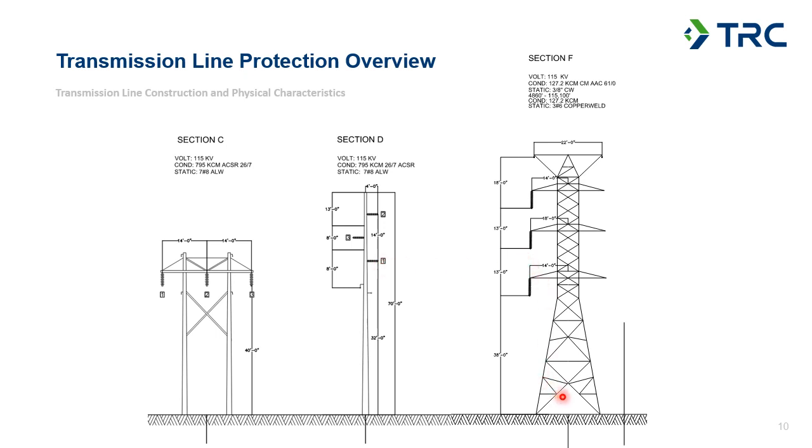This type of structure would be designed to hold two separate transmission lines because you've got 6 points here you can connect. So you could have phase 1, 2, and 3, and then another line on this side, or they can be spread out between the different points here based on the design considerations.